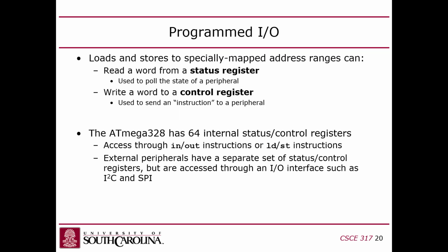Okay, so I mentioned last time about programmed I/O. All of this stuff, setting up these hardware devices or doing GPIO and having the software interact directly with the pins, is done through programmed I/O. There's this idea of a status register, which are flags in a register that is visible to the software. The software reads a register, or actually it's reading a memory location, because each one of these registers is mapped to a memory location.